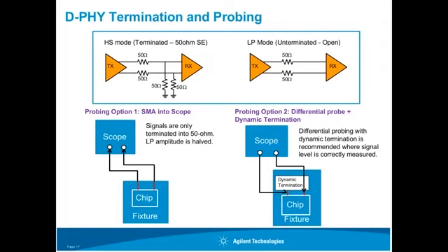Okay, thank you. Can the scope protocol decoder decode M-PHY low-speed PWM packets as well? Yeah. So maybe it's not very obvious in my slides. The protocol decoder that we offer for the M-PHY can recover the clock from the high speed, as well as the PWM and sys clock.